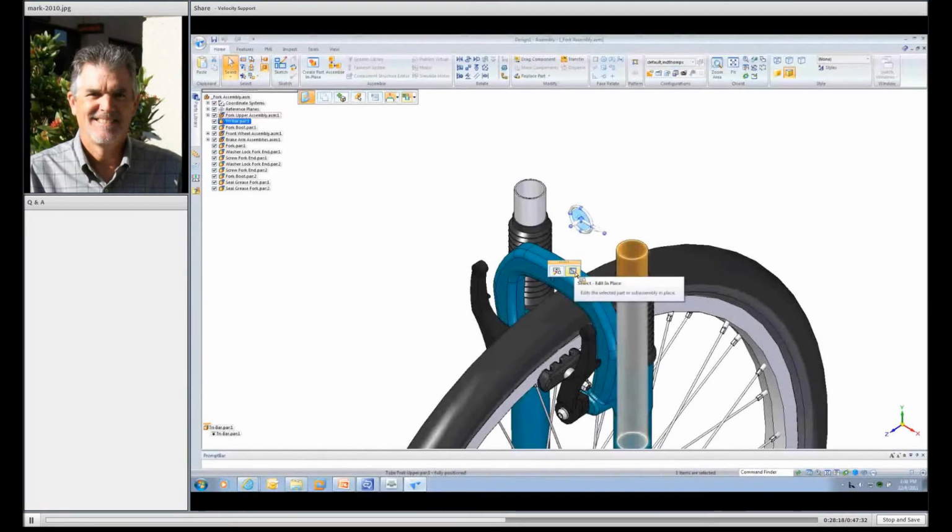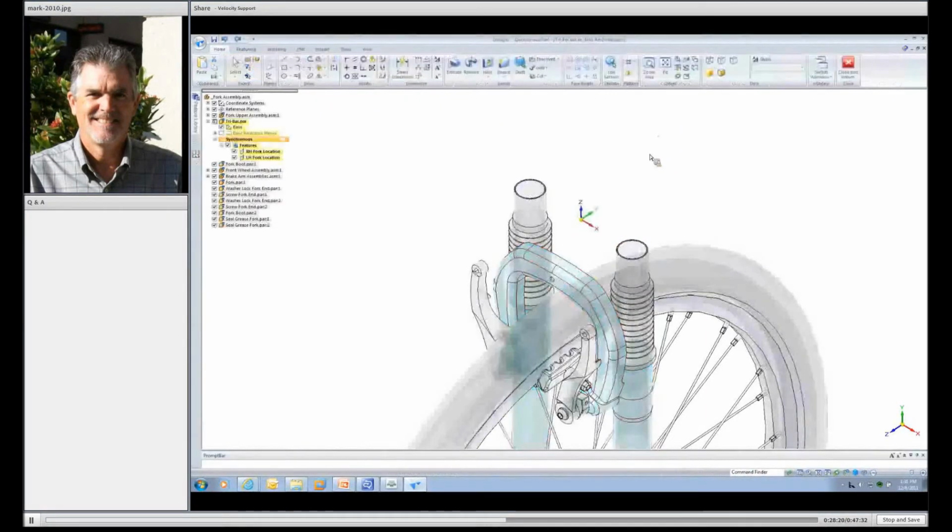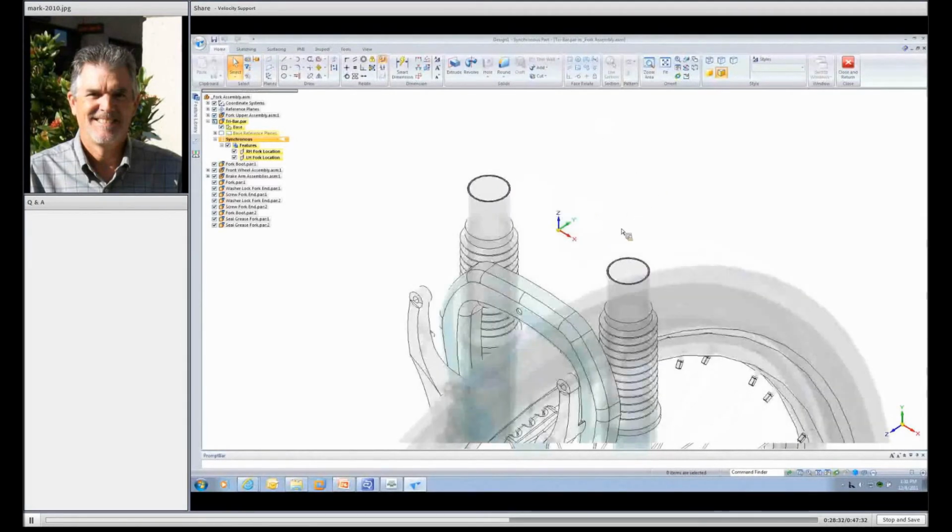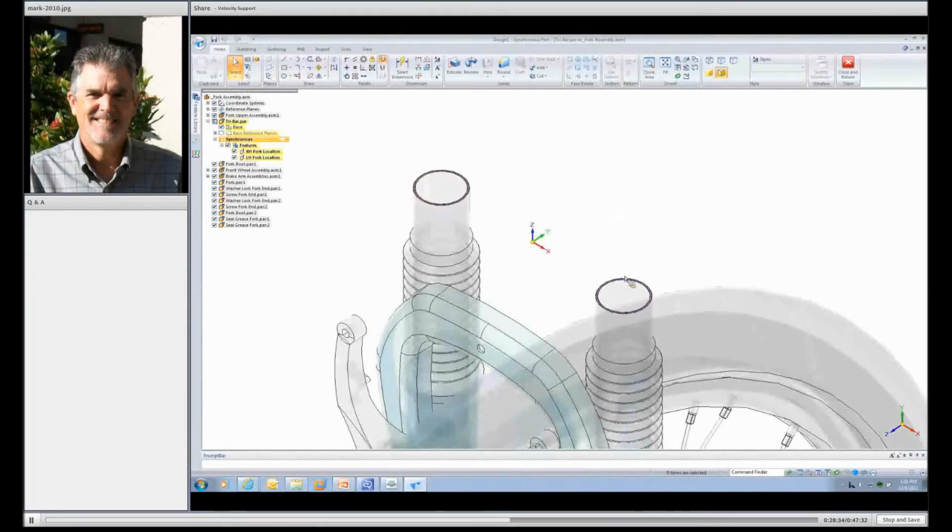They kind of infer, depending on what orientation you are in the view, what plane you want to draw in. In this case, we've got the XY plane, but you'll notice the crosshairs change if I go to the YZ. If I get into the YZ plane, they change to the YZ plane. So let's lock into the XZ plane, and you'll notice too that you can either click on the lock, or if you look at the prompt bar down below, you can also do a simple F3, which will lock you into that same plane.